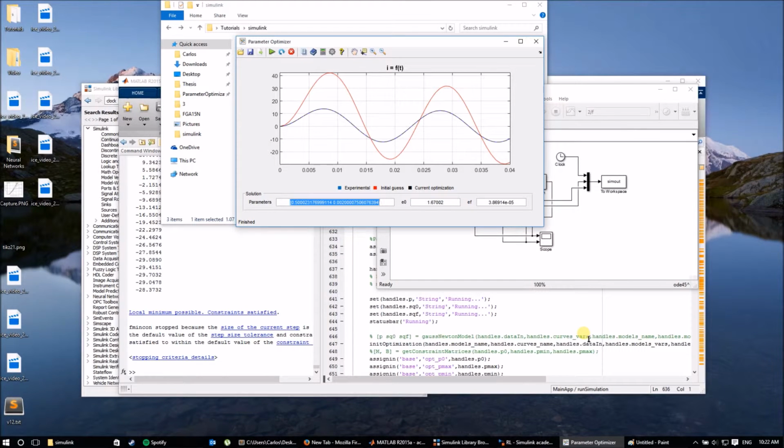So if you have a model that depends on the previous variables, you always have to be aware of that. If you simulate in a short period of time, it depends on the system, but let's keep it simple, it may be okay to just initialize your variables to the value they must have. But if you simulate for a long period of time, for example, I simulate for several seconds with my machine, you can see that if you try this way of just initializing the variables, it will not work because the errors will just pile up.